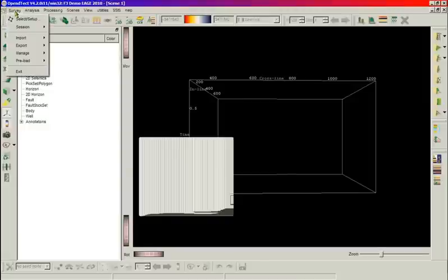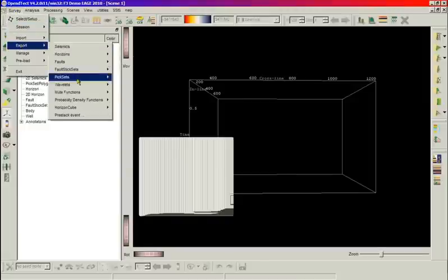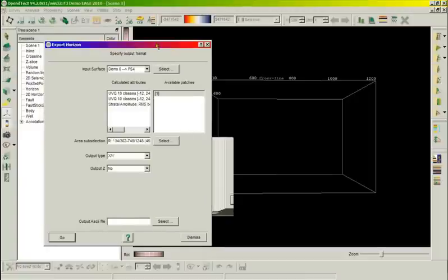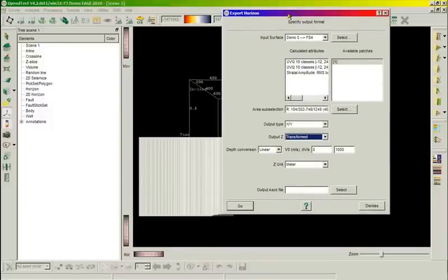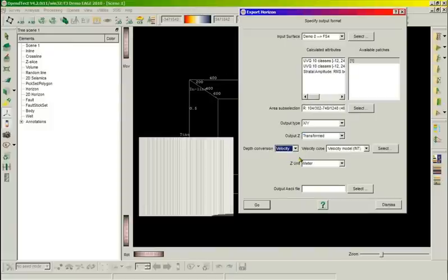Once again, before we go to the depth survey, I'll show you one more new option in 4.2 concerning this export of horizons: you can do the conversion using not only velocity models, but also using either a linear trend, so V0K, or using the depth time model of a loaded well, like F3 on this data set.